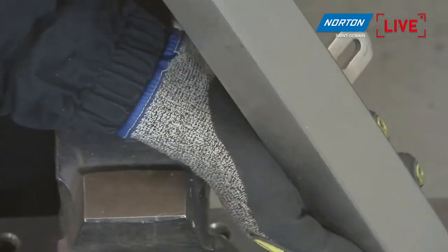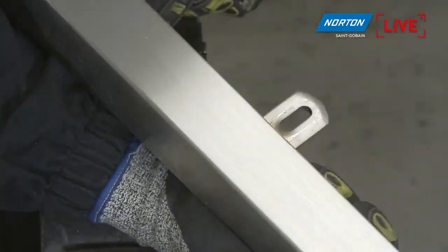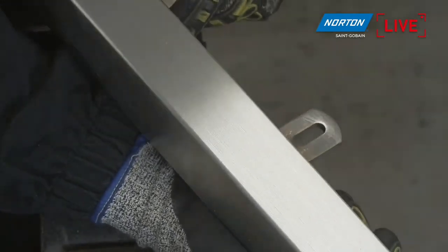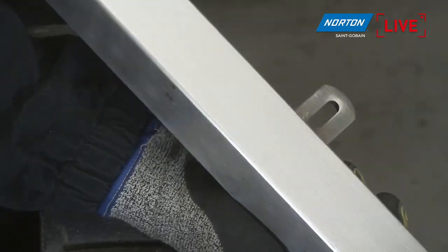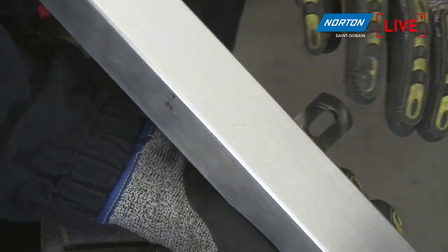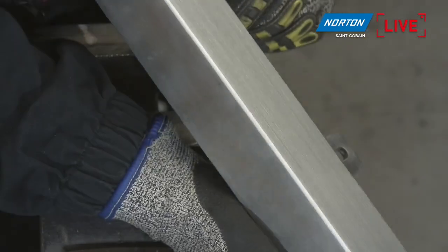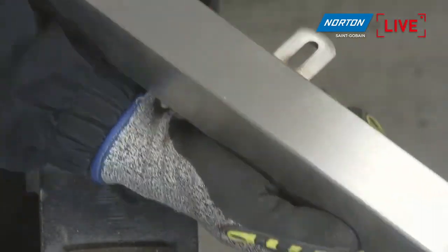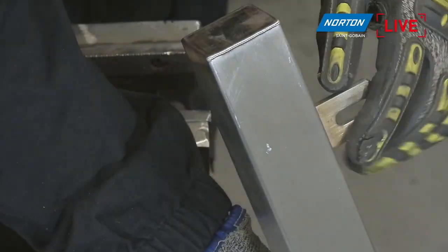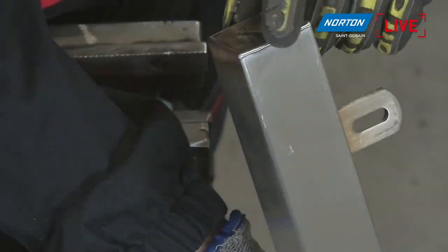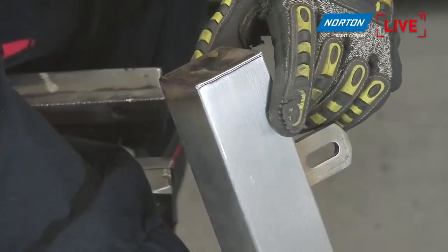And we get this really, really quickly. You can see nice linear scratch, which is perfect for stainless steel applications, again just to show fewer fingerprints or less muck or damage as it's in service. But you see that medium heavy duty pad gives us a really nice finish extremely quickly. And look at that there. That burning from the weld is completely gone.